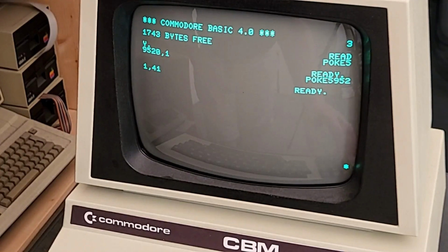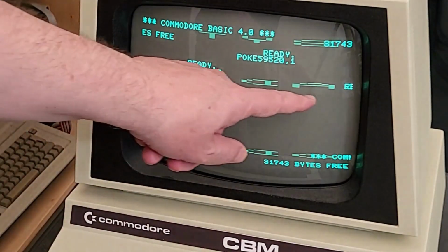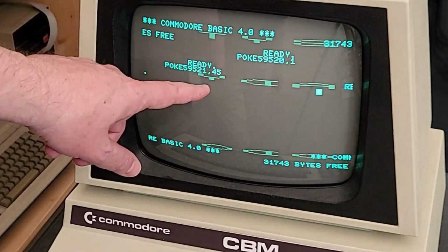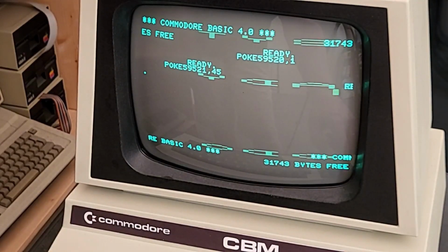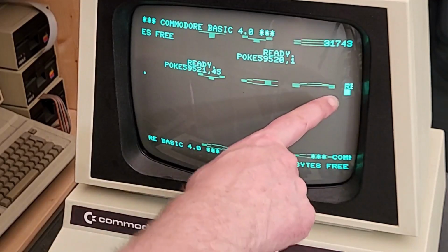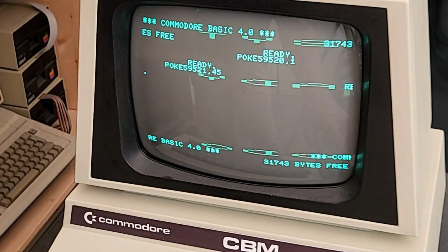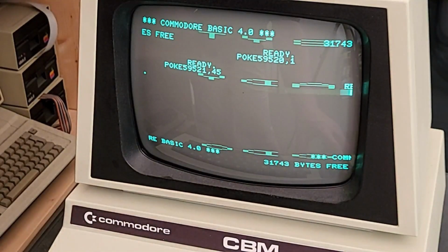But we can even go any further. So what's happening now? What you see here is these other, kind of characters which are very wide and are turned and are mirrored. And the reason for that is now we have so many characters that are being displayed. The display is going over the horizontal sync and it's going into the retrace. So if I move the cursor to the right, you can see how the cursor is underneath that ready prompt, which is basically seen here, and I can move one line up, and then you can see the